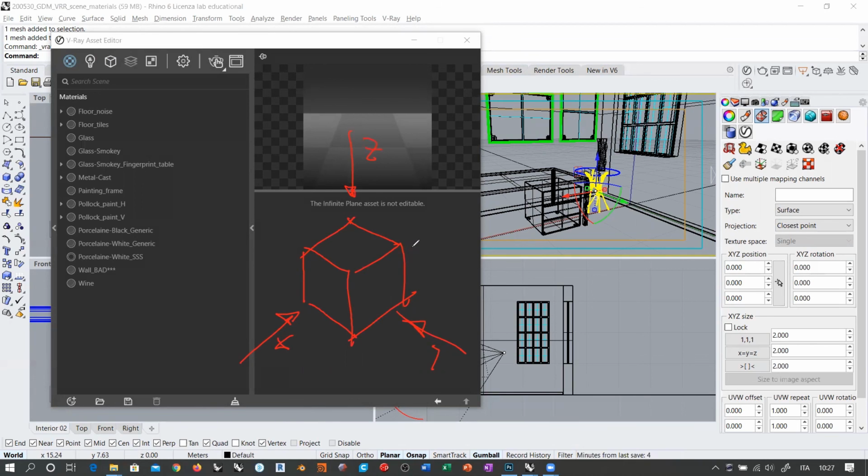And triplanar texturing allows also to create blend zones between these 3 directions. So if you have a cube, you will have the texture exactly projected onto this face and to the opposite face, of course. But if you have some organic shape and you use triplanar texture, then you can blend this texture projected onto the surface of this object in these areas.